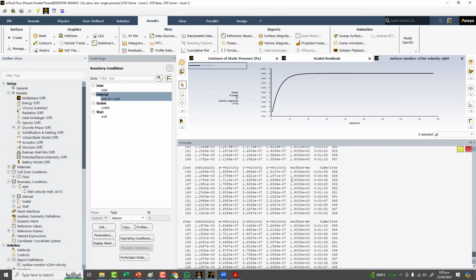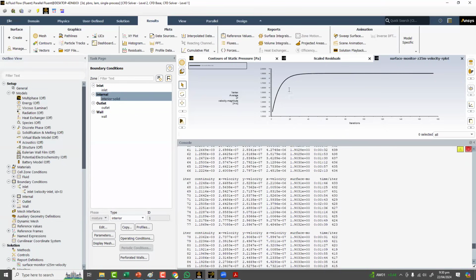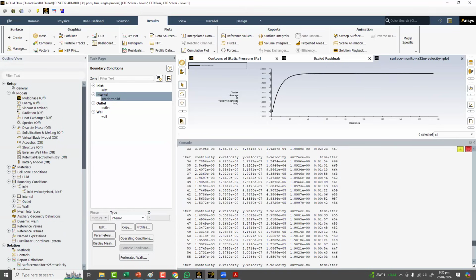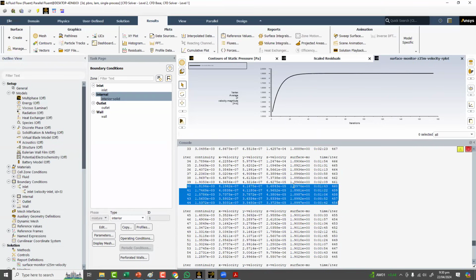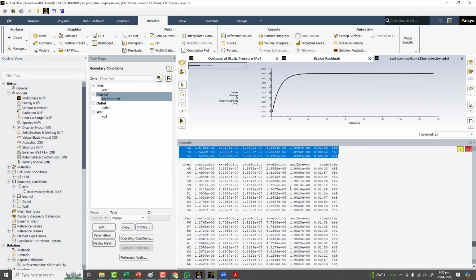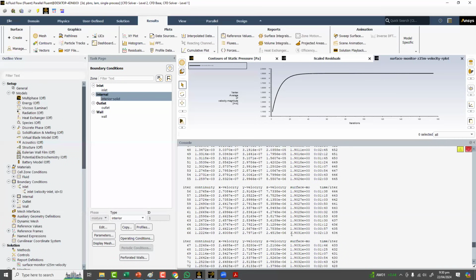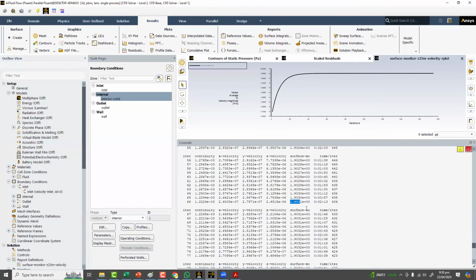You can see after about 40 iterations, go to 40 iterations based on the graph, 20 iterations maybe, but go for the 40. After the 40, the value of velocity at the center point at z equal to 25 meters is 1.897, so 1.89, 1.9, so 1.9031. So at 66 iterations, like over here, after this point onwards, the value is not varying.